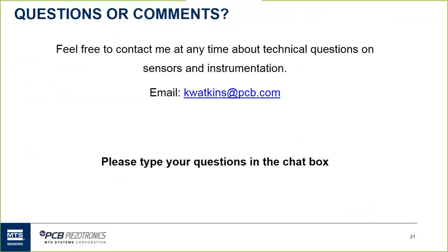Piezoelectric accelerometers have been used for temperatures down to cryogenic, which is typically minus 320 degrees Fahrenheit, and which is commonly used for certain applications, specifically involving rocket motor fuel pumps, fuel chambers, etc. For higher temperatures, we have accelerometers in our catalog on our website that are good to 1,200 degrees Fahrenheit.